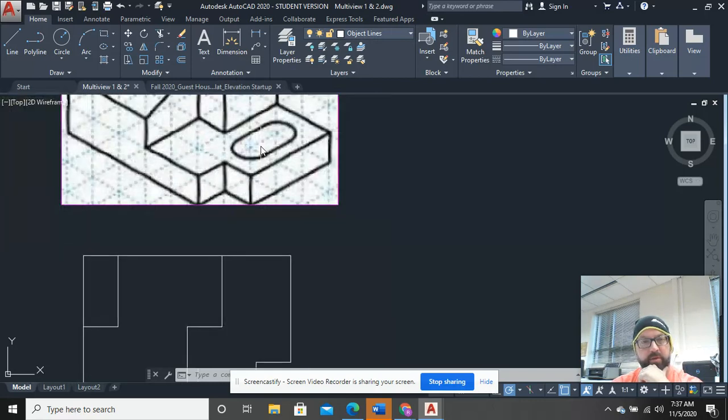So if you look at this, this kind of clears it up a little bit. This intersection right here, this point on the grid and this part of the grid, they're 1 inch apart with a 1-inch circle. So how do I figure out that position? Well, if I offset 1 inch from the right, it places me right here, correct? So now this is really not part of the drawing. So again, to sort it out and keep myself squared away, I'd put that on a construction line, okay? And if I come 1 inch down this line from the back, then I would get a center for that circle. So I'm going to go ahead and offset 1 inch.